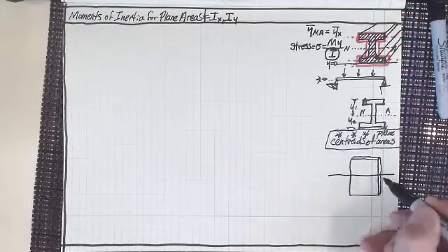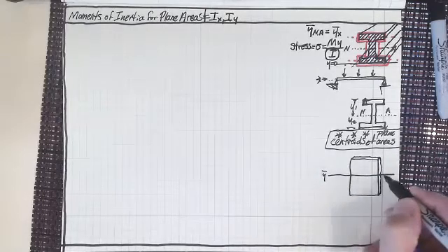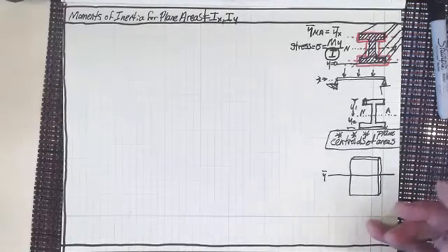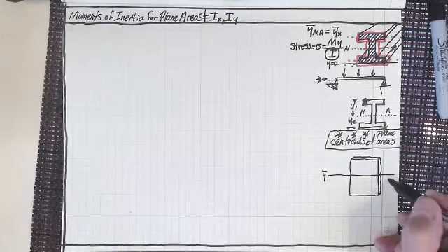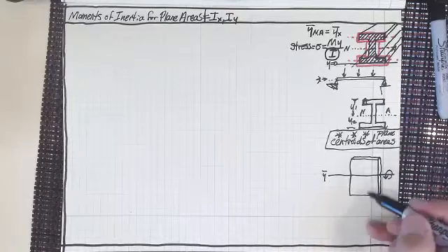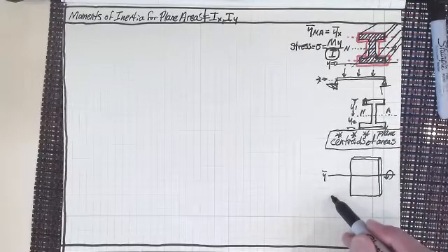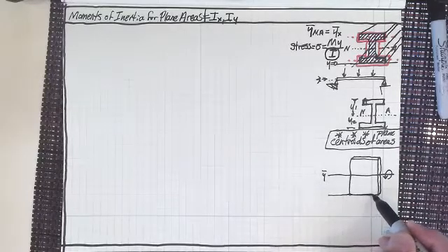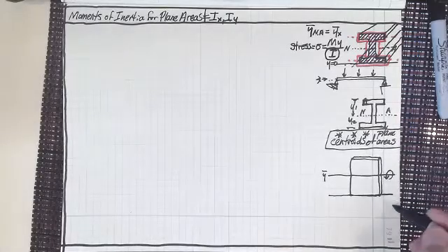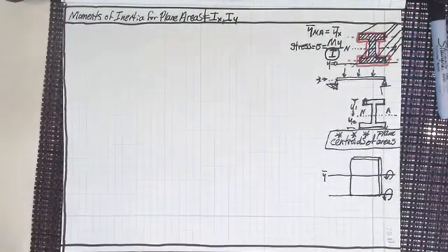Now, if I was to take this sheet metal piece and weld right across the centroid, this is the centroidal axis, so this would be Y bar. If I was to weld across there just a thick piece of wire, and rotate that steel around there, sort of like a little flywheel, right around the center. And then I was to take another one and weld a piece of metal down here, and rotate it around there, which would take more torque to start rotating and to keep it rotating.